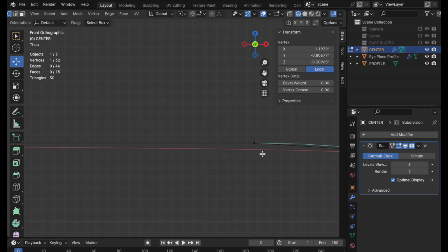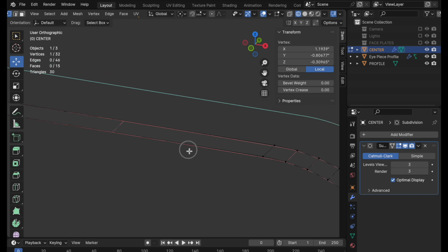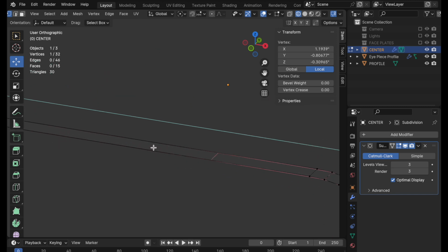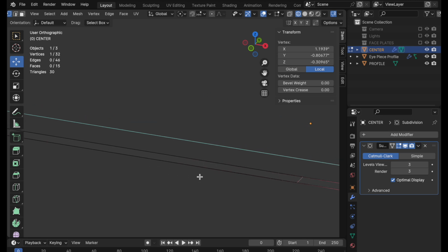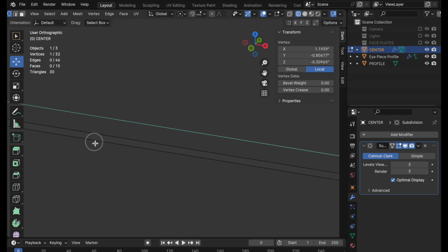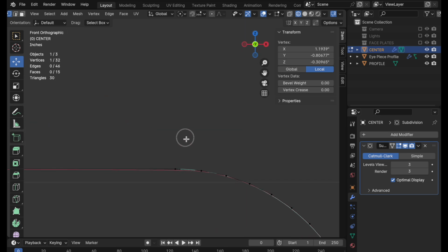And in fact, because it's subdivided, it's going way into the long flat area because we don't have another edge till way over here. Okay, in fact, we don't even see it. In fact, maybe I don't even have one anymore. Yeah, I've got one way over here. So the subdivision mechanism is producing that curvature into the straight areas, and we want to resolve that.